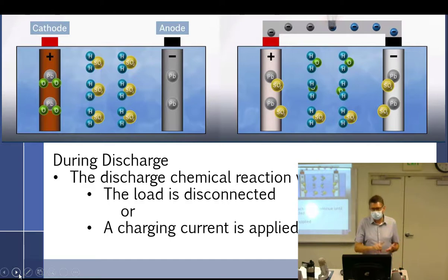Now, if I'm using the landing light, taxi light, every load I have on the airplane, and the ammeter says 0, what is that telling me? The alternator's providing all the power for all that stuff. It's just telling me what goes in and out of the battery. So if it's at 0, it means the battery's charged and it's pretty much happy.